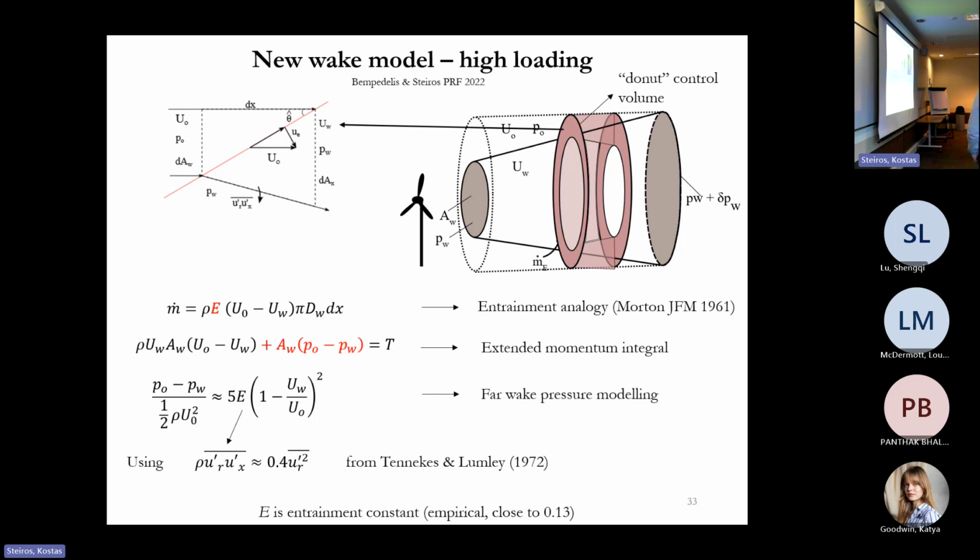This is the closure of the pressure term, which until now has not been modeled or considered in these settings of wind turbines. You can see that it's a quadratic function of the velocity difference, outer minus inner, times the coefficient T, which parameterizes turbulence.